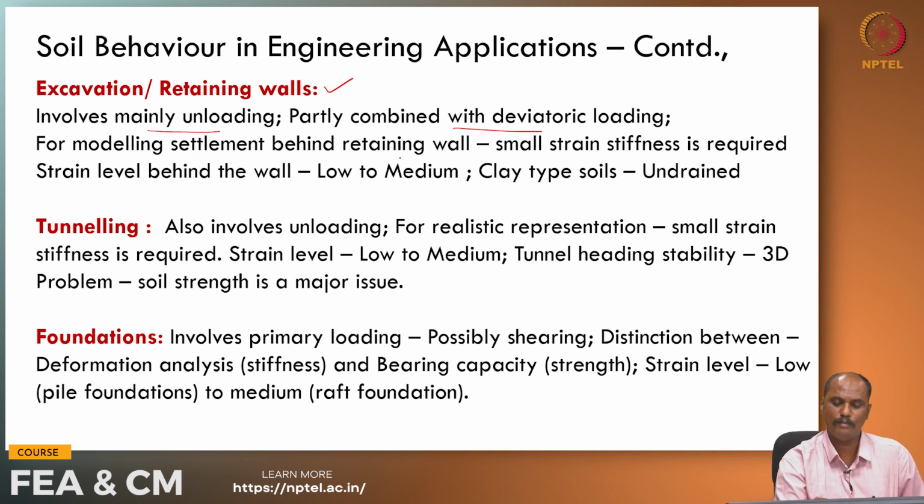For modeling the settlement behind retaining walls or excavations, small strain stiffness is required, and that has to be noted down. The strain level behind the wall could be between low to medium. As I would like to recall, the range of strain levels that we encounter in geotechnical structures is usually between 0.01 percent and 1 percent.